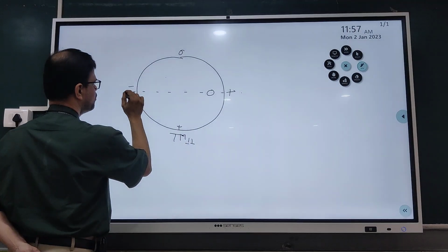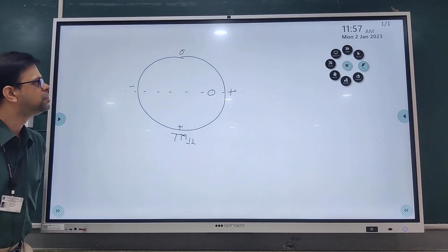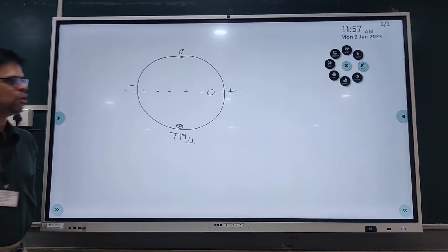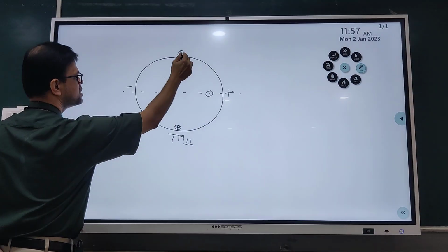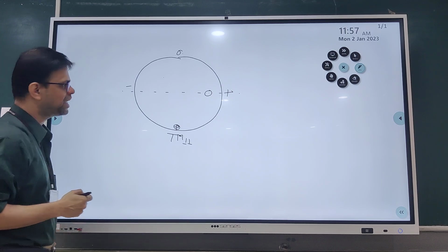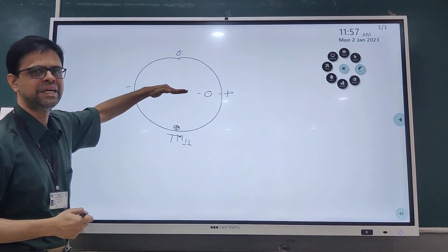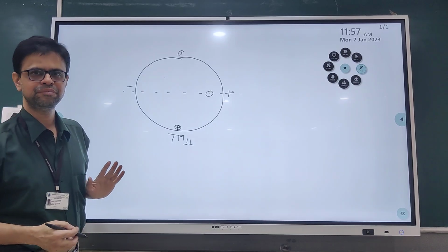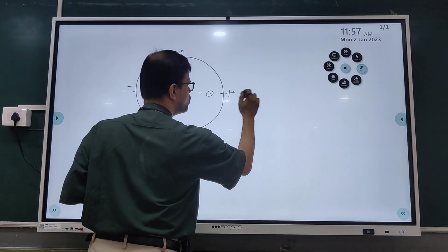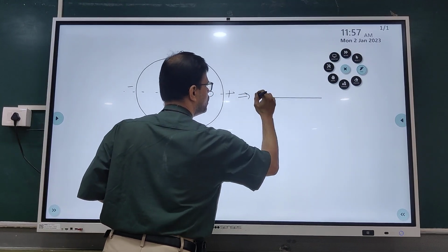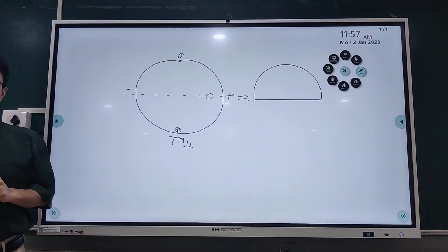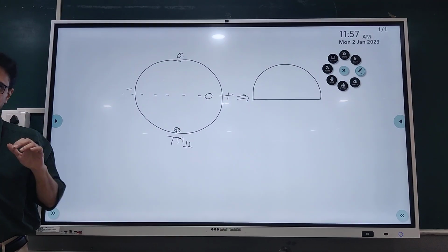Now you will see, with respect to the coaxial feed, you have a symmetry because this is plus, this is minus, this is 0 and this is 0. So with respect to this center axis or the coaxial axis, the fields are identical. So in that process what I do is realize only half of the circular patch, basically a semicircular microstrip antenna.